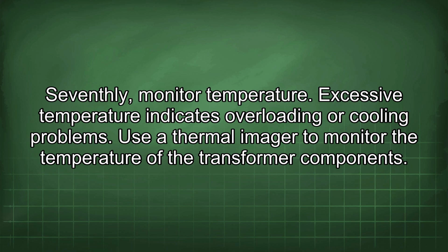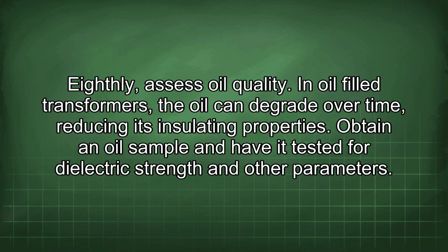Seventhly, monitor temperature. Excessive temperature indicates overloading or cooling problems. Use a thermal imager to monitor the temperature of the transformer components. Eighthly, assess oil quality. In oil-filled transformers, the oil can degrade over time, reducing its insulating properties. Obtain an oil sample and have it tested for dielectric strength and other parameters.